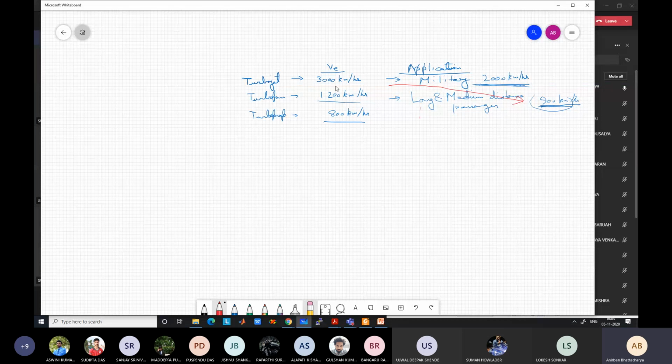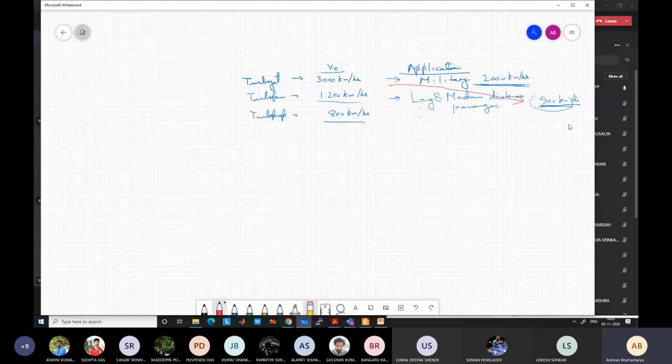Turbojet will provide a lot of thrust for the civilian aircraft, sir, but because Vi is small, a lot of fuel will be wasted, right? If we can get the same amount of thrust using a turbofan, in which del V is less, that's better. Yes, that is true.